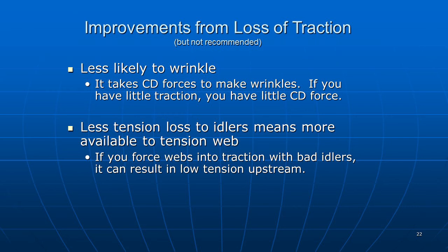We do have examples of that in bow bars and D-bars, and the operators invariably find that if you stop a roller from turning, it may solve a wrinkle problem. So certainly not a recommended solution, but the lower the traction, the less likely your webs are to wrinkle.